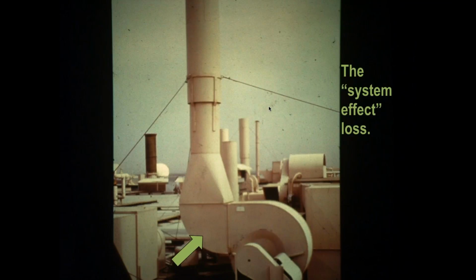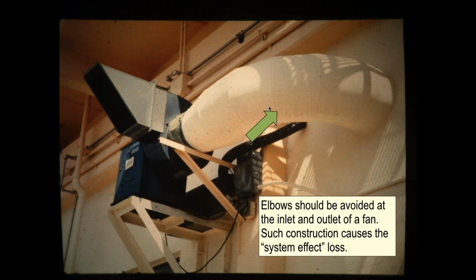Now you have something called system effect losses, and system effect losses are associated with turbulence in the vicinity of the fan. For instance, right here, there's so much going on in this fan already. Remember, we saw that service factor. We're going to lose 10% of the energy going through that fan.